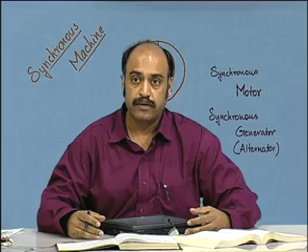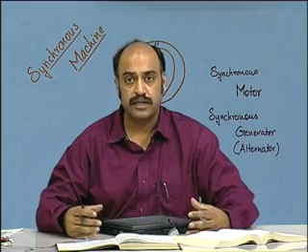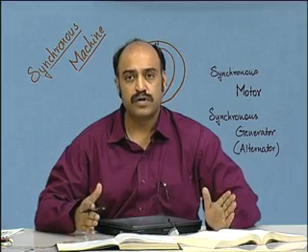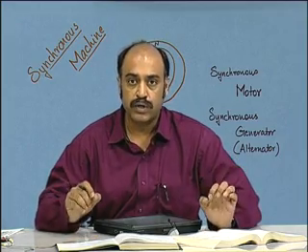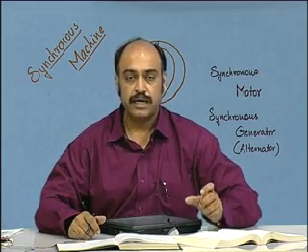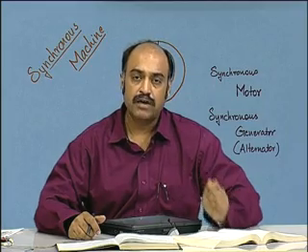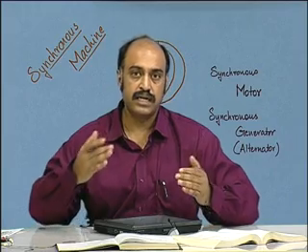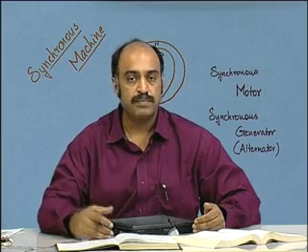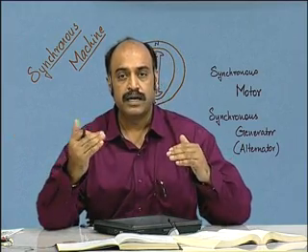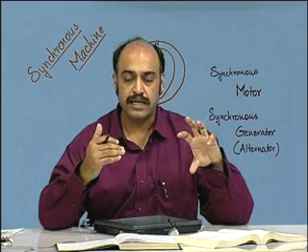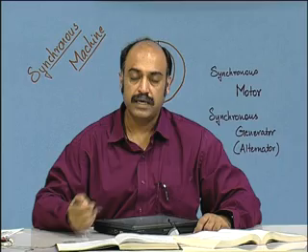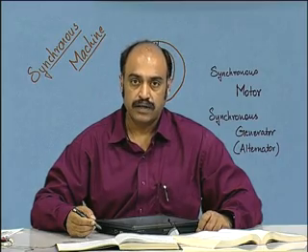In industrial loads, where there are large industrial loads with lagging power factor, a synchronous motor is put with just no load and it is connected to the mains, and the excitation of the synchronous motor is so controlled such that EB is at such a position that it compensates for the lagging power factor of the load, and overall the AC supply can be made to see just unity power factor by means of this synchronous motor.